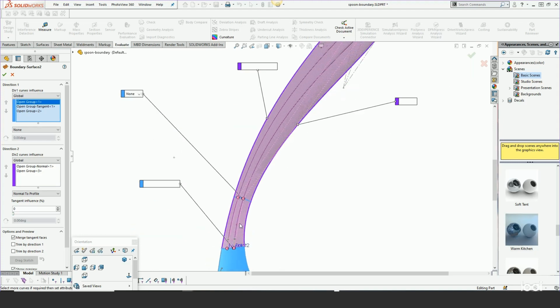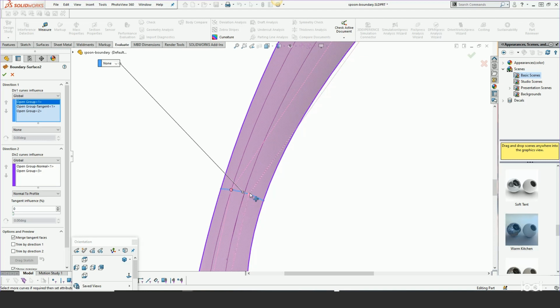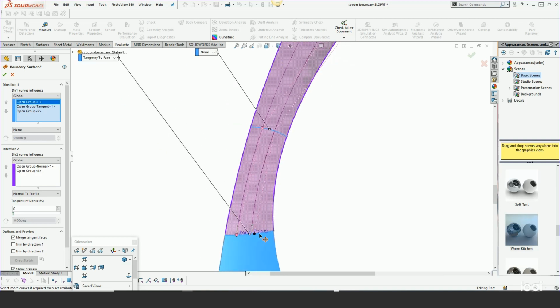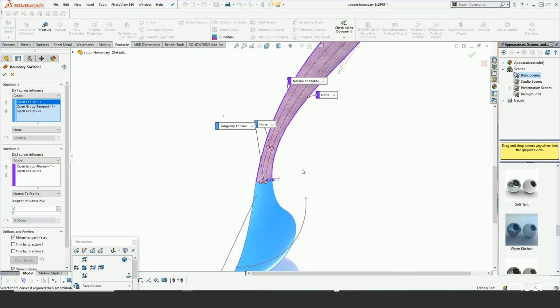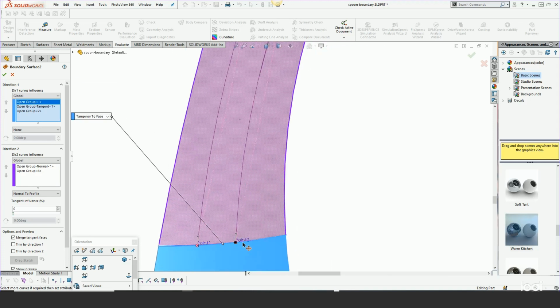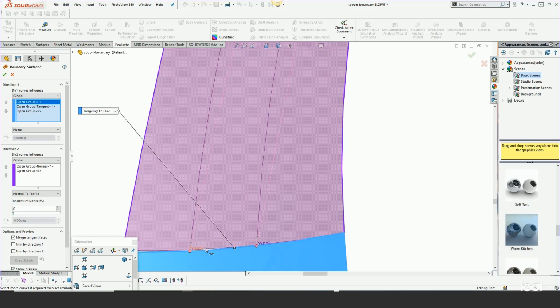And you can see, if I start pulling these around, these interim edges will actually update. And that's where it becomes very powerful to be able to influence how the surface is actually flowing. And that's why I put connectors here, because I want these to somewhat spread apart. And you can see that I've actually created some points in a sketch. And that's a good thing about boundary connectors, that you can actually snap to geometry, and that's what I'm doing here. So they can be parametrically driven.